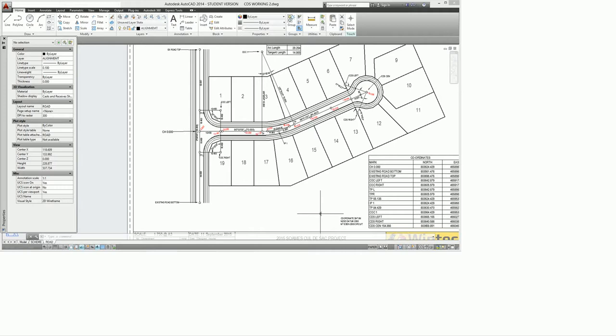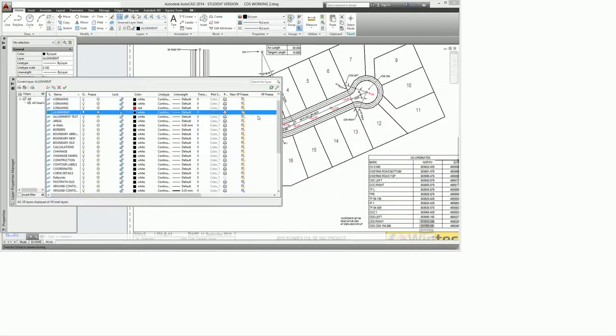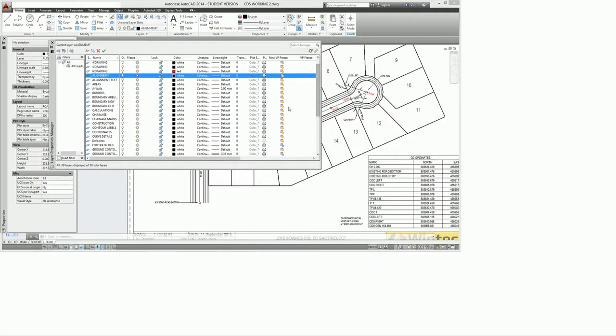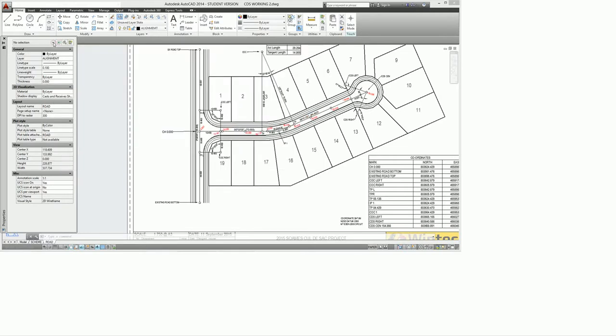Just a few little things that came up in the course of this, and that is that if you create some new layers, depending on how you create them, for instance if you create a new layer, it creates a new layer in every viewport, unless of course you use one of the options such as create new layer viewport frozen in all viewports, which is that one there. It's a good one to use, because it creates a new layer that doesn't appear in previous viewports.